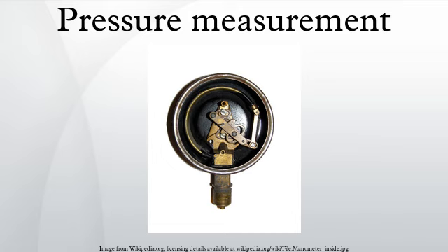Although no longer preferred, these manometric units are still encountered in many fields. Blood pressure is measured in millimeters of mercury in most of the world, and lung pressures in centimeters of water are still common, as in settings for CPAP machines. Natural gas pipeline pressures are measured in inches of water, expressed as inches WC. Scuba divers often use a manometric rule of thumb: the pressure exerted by 10 meters depth of water is approximately equal to 1 atmosphere.